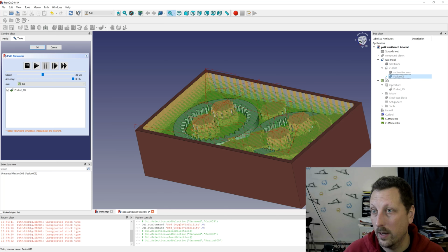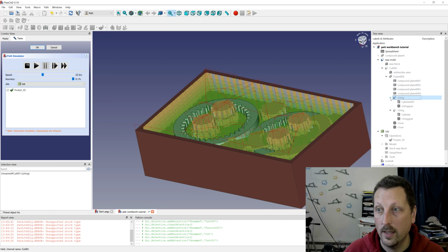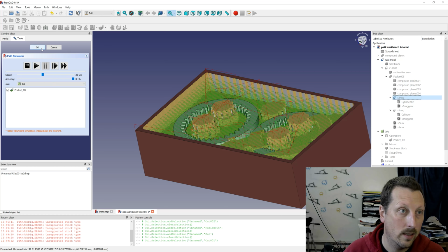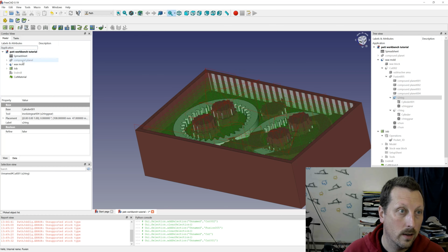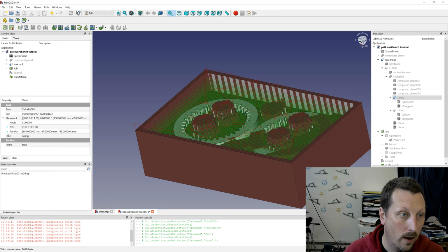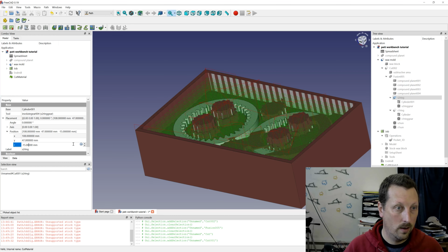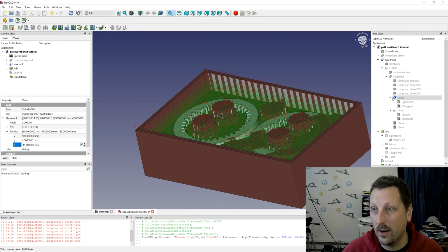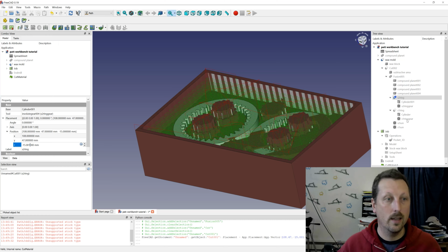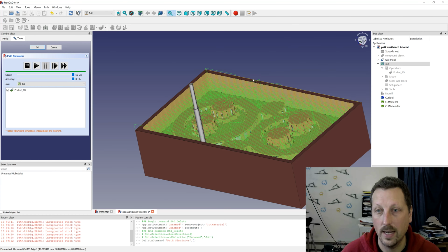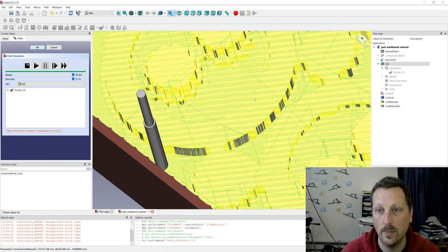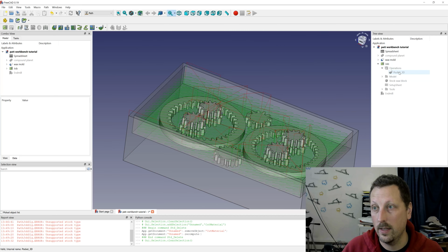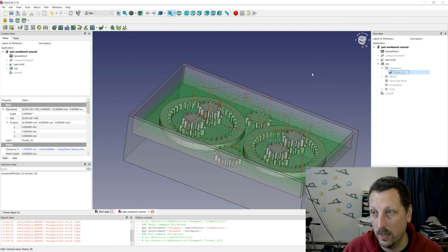cut 02 and our fusion and our rings, right? These are positioned. They need to... okay. So we're done with that. We need to drop them by 0.001 millimeters, right? The rings aren't actually touching the bottom technically. We should see that it's roughed out and it left our rings this time. Perfect. So this bulk removal job looks beautiful now.